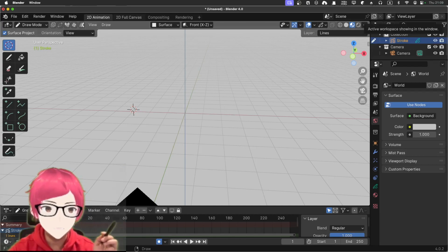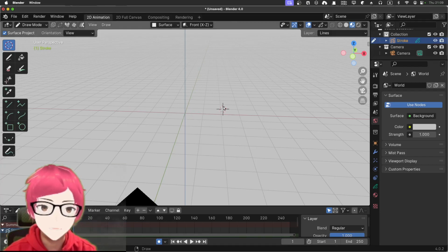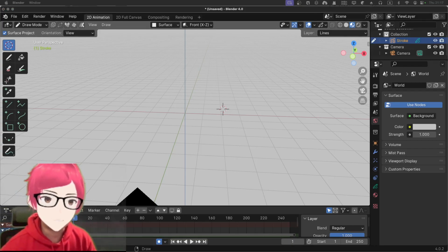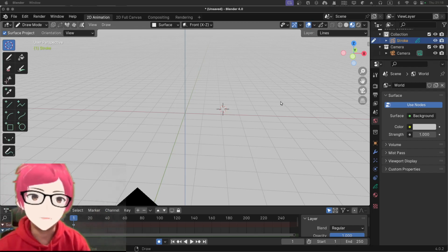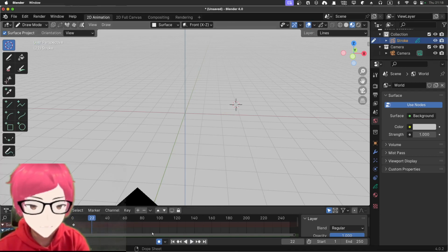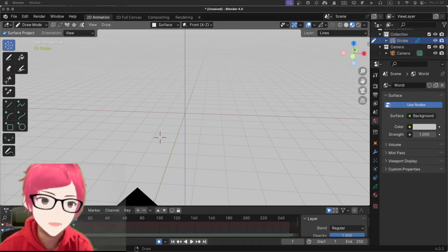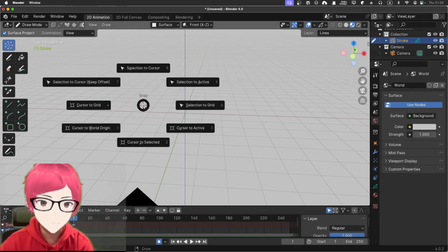When I'm doing this 3D modeling, normally when I like to set the cursor back to origin, I use the shortcut, and the shortcut is Shift and S. So we got the wheel coming out, and then you can select whatever you want to do.